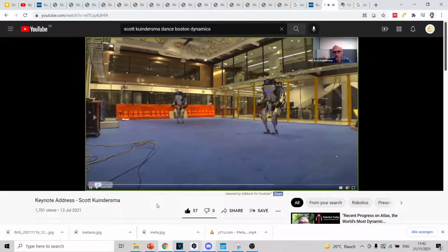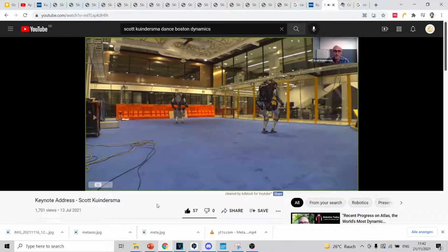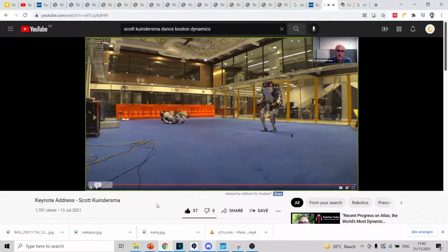So here's some network communication that's happening that's triggering behaviors on multiple robots. They're just doing some of the standard 180 jumps, and then they'll execute the same dance routine together. The question here was, can we start them together with reasonable precision, and will the open-loop time tracking happening on both robots be enough to keep them in sync? And the answer is basically yes. We didn't have to do any timing feedback across robots to make this happen. Each robot was independently good enough at tracking its own time.